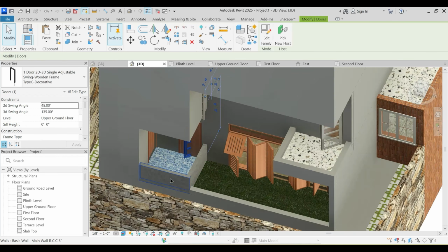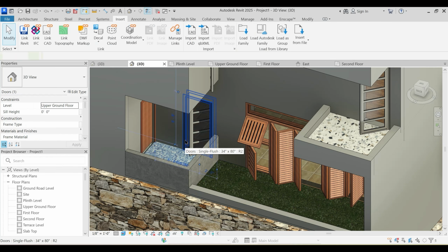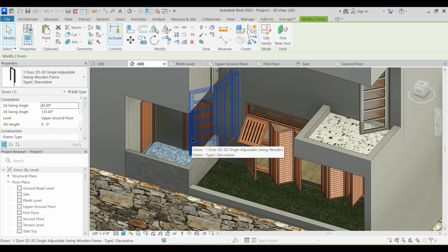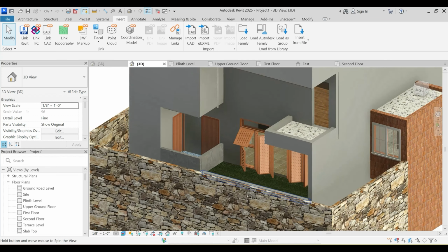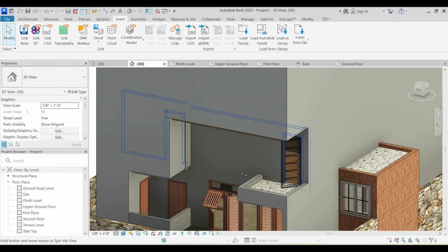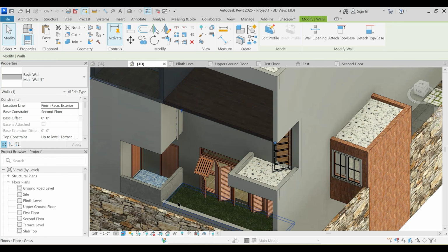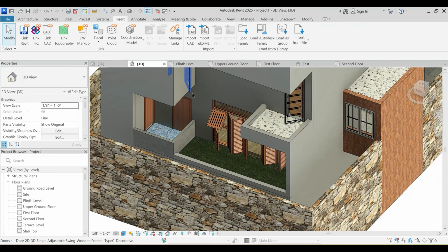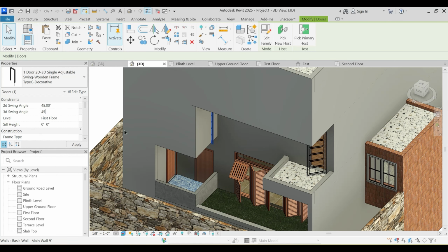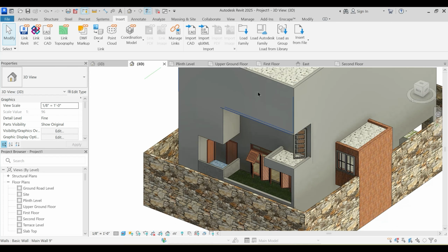Okay. And why is this reflecting two doors? There should be only one door. And if this is, oh yes, the door is off inside. Let's change the swing angle to 45 and we won't have a conflict. Okay, now this particular one here, let me just make this door also 45. And here there will be a beam at this level.